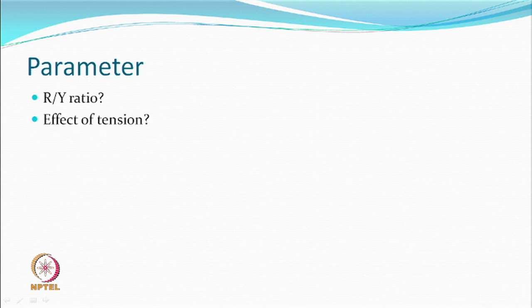In this case also, the tension would be there, and tension control has to be done, because you can't say that there will be no tension, as you still have a situation of a draw ratio in a draw texturing machine. So, you will be pulling the yarn in any case. You cannot have a situation where the yarn is being held at the nip.